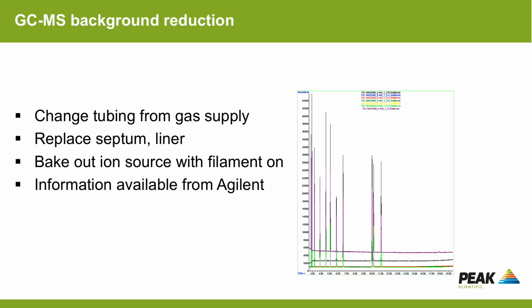And the chromatograms that you can see on the right hand side here, this is an overlay of the same essential oils mixture being injected day after day. What we can see is that from the third day onwards, after changing from helium to hydrogen, we see the baseline has settled to a constant background level. But there can be higher background initially after changing carrier gas.